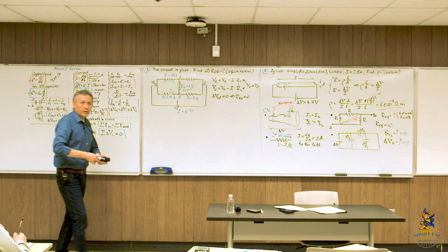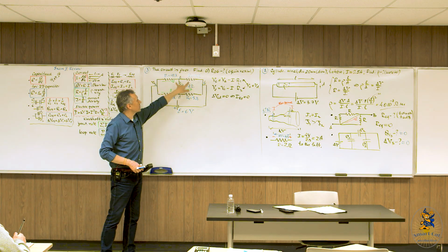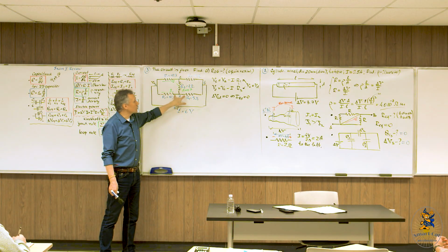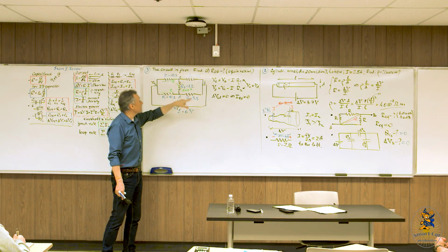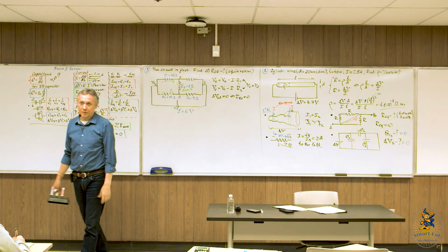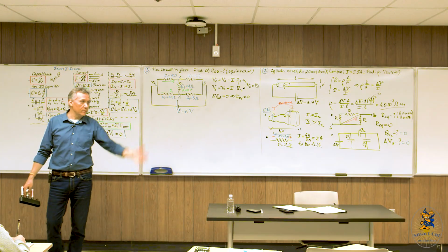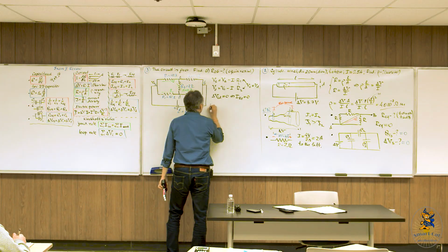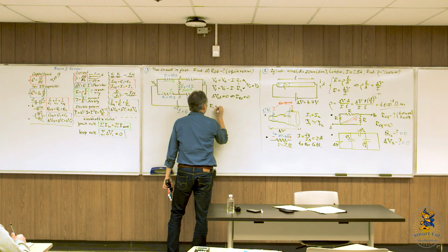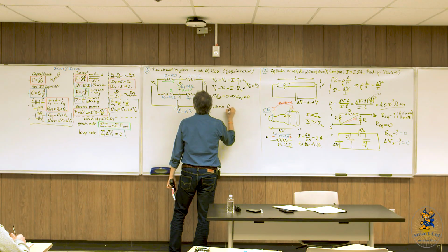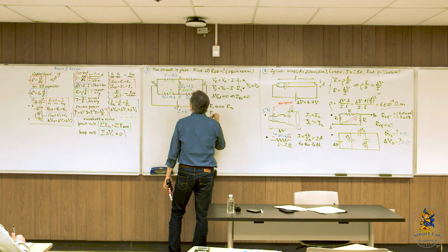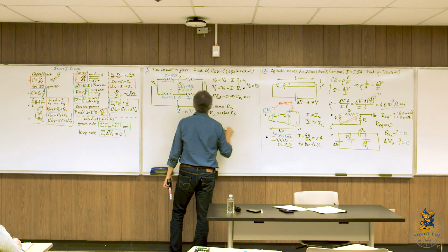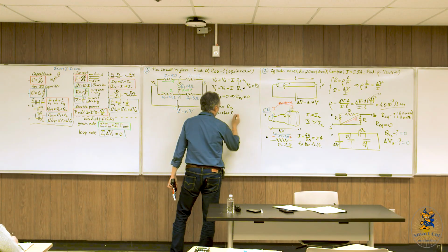Of course, everyone sees how these two resistors are connected. Of course, series. These two also in series, and then this in series is in parallel with these guys in series. Right? So now the rest is trivial. Again, it's like your take-home quiz. So now R1 is in series with R3, and R2 is in series with R4. R5 is out.